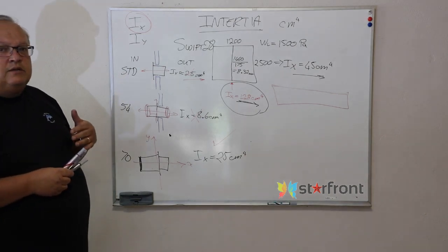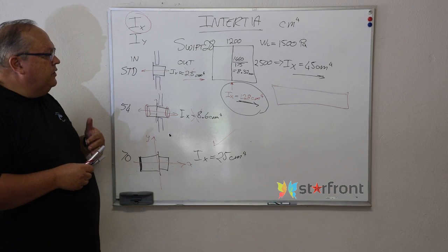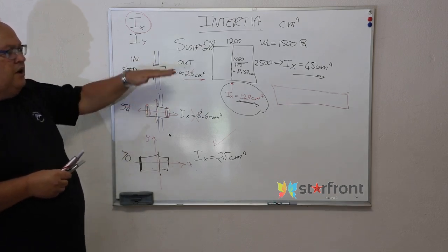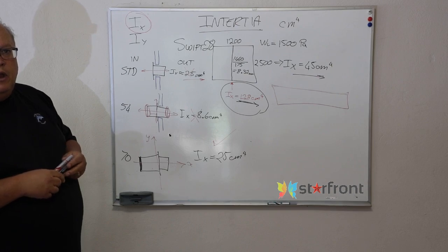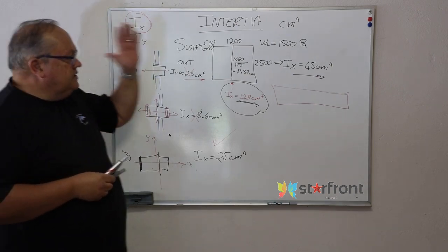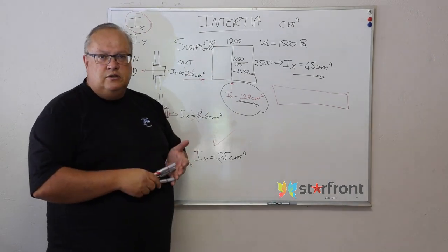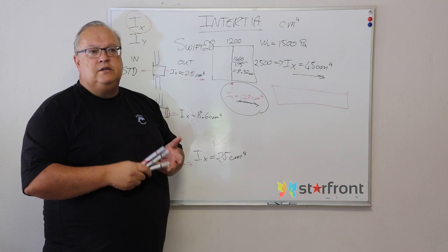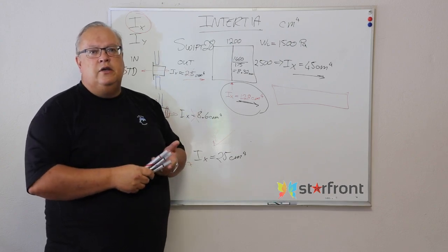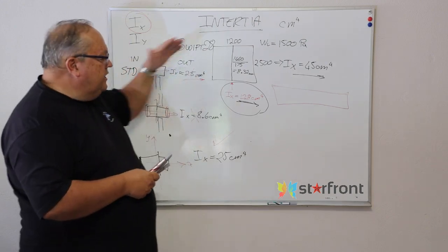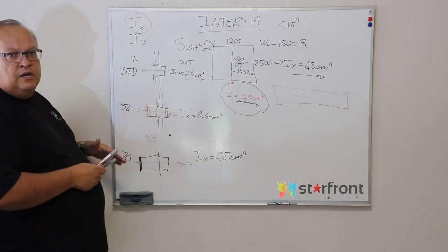And please realize that it is part of the National Building Regulations to ensure that you are specifying the correct profile. And that does not only apply to mullions. Remember, the exact same calculation applies for transoms, it applies for interlocks, and meeting styles, where two door styles come together on a double door or on a Vistafold door. So this calculation needs to be done several times.